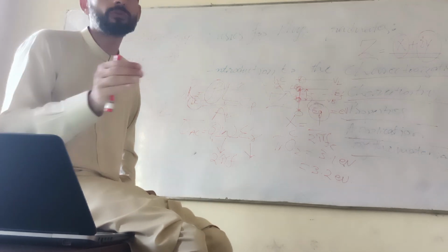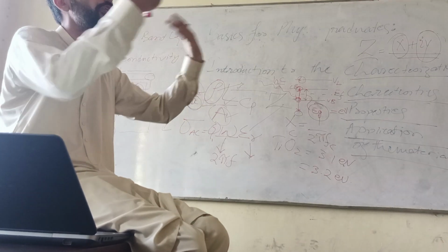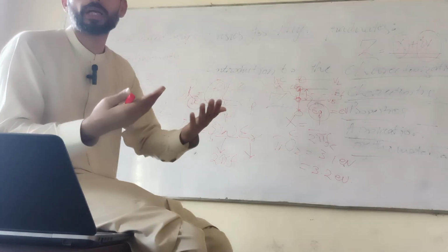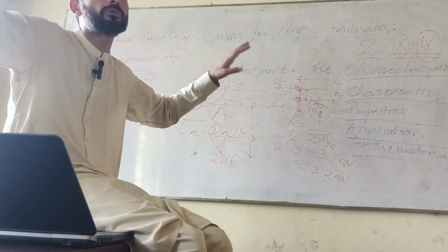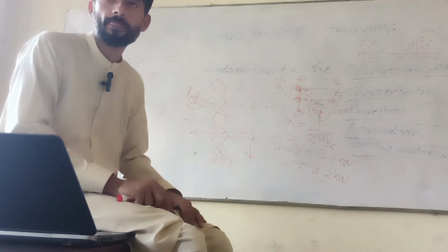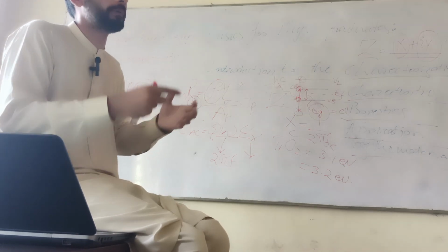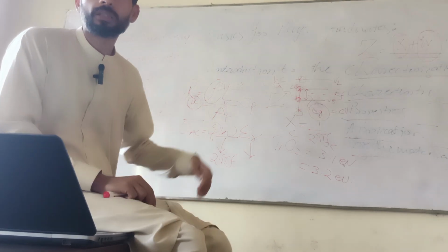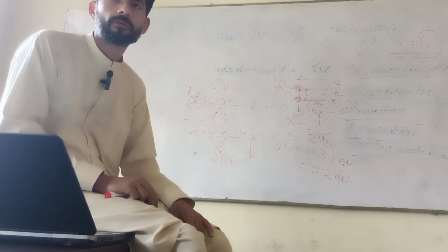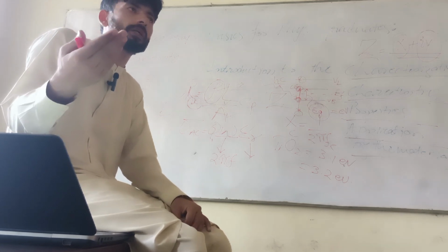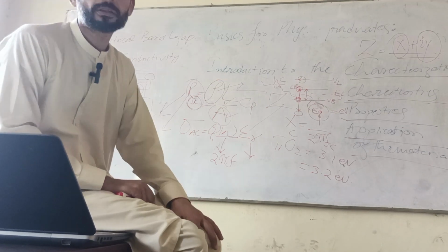There are low resolution and high resolution. This is for atomic scale; you can even identify this. You can see these spaces with your naked eyes through such techniques. However, it is impossible with XRD. XRD just gives you a pattern, not real-time pictures. There are so many limitations of XRD. If a composition is less than 5% in the total range, then this technique will be unable to identify it. If something is 0.001%, then how can you identify it?